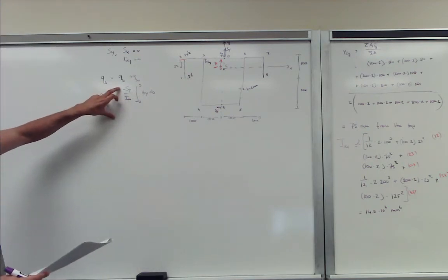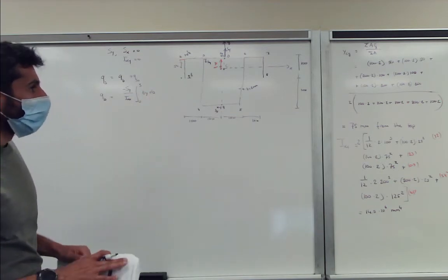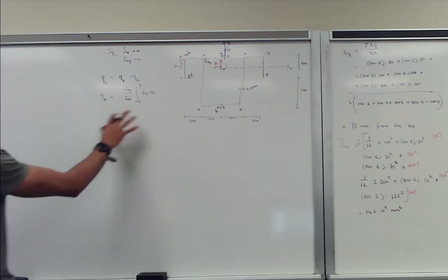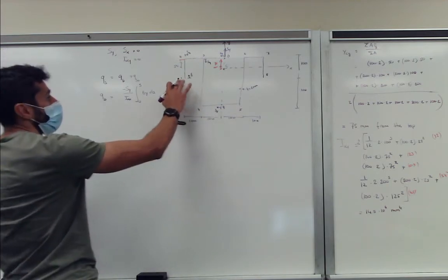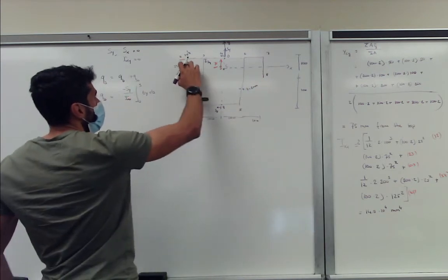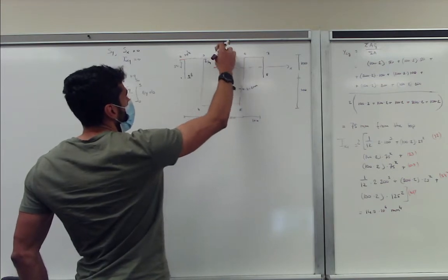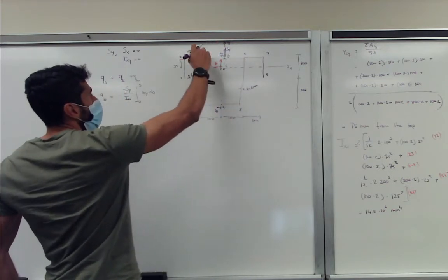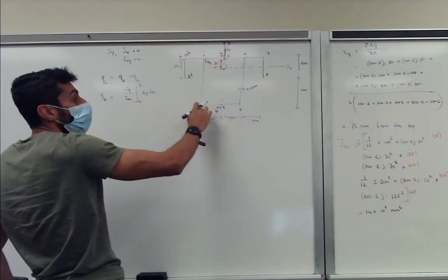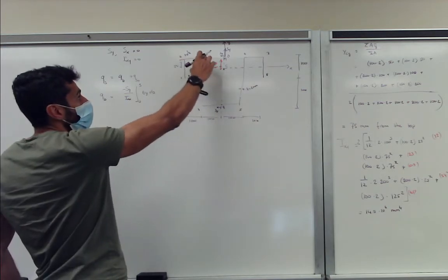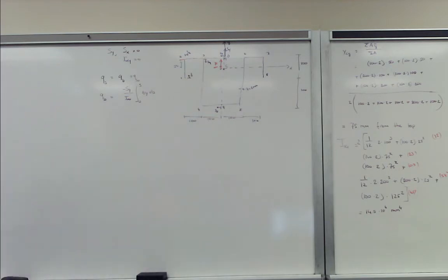We have our shear force given, so we can do the evaluation of the integral. So the question is, where do we start? Of course, we're going to start at an open section. So we're going to start at point position 1 or 8. We're going to go from 1 to 2, 2 to 3, and then we're going to cut open the closed section at point 0, and then we're going to go from 0 to 3. We calculate where the total shear flow is at 3, coming from the left and from the right, and then we go to point 4. So we cannot go to point 3-4 before we have made the cut and come in from the right as well.